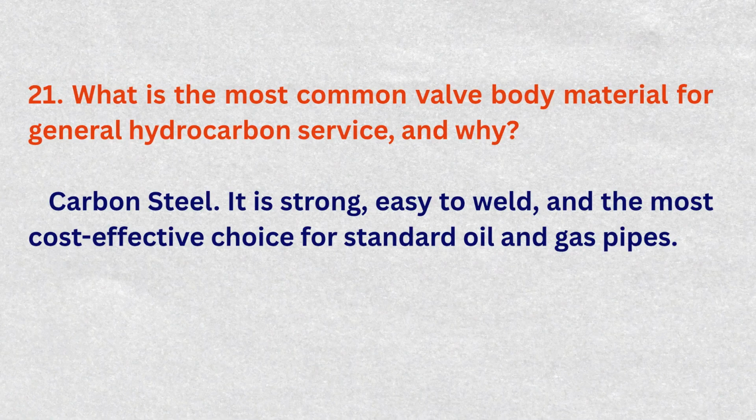What is the most common valve body material for general hydrocarbon service and why? Carbon steel. It is strong, easy to weld, and the most cost-effective choice for standard oil and gas pipes.